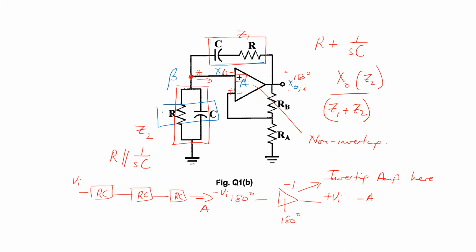If the phase shift network gives you a 180 degree phase shift, then the amplifier has to compensate by giving the additional 180. A 180 degree phase shift is an inversion, right? So the amplifier will have to have a negative gain, in which case you use the inverting input, and the inputs you will see will be going to the inverting input of the amplifier, right?